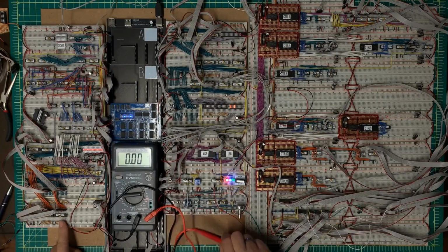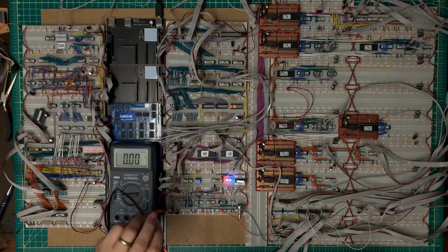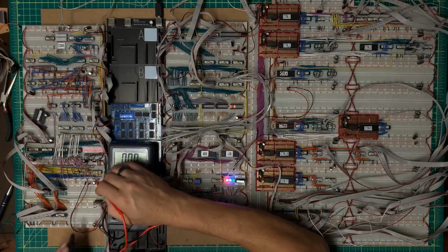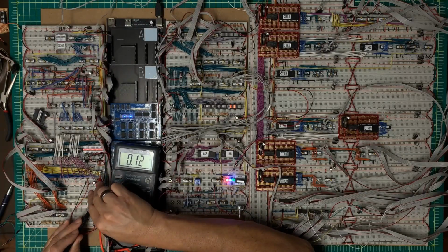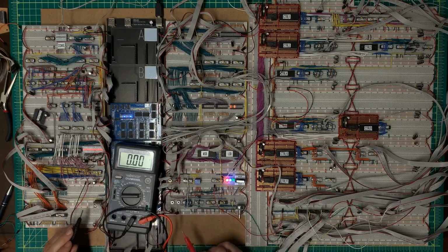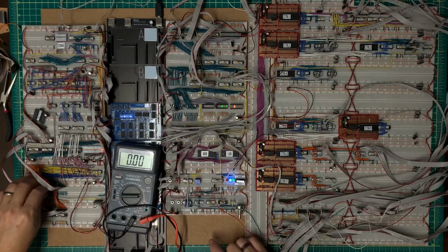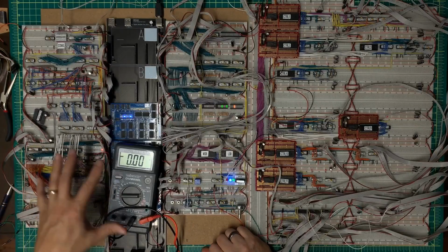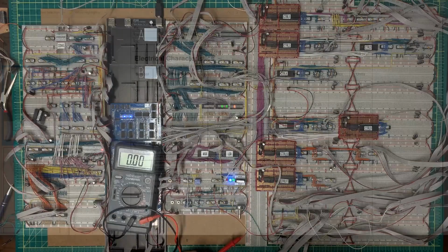Now, to make matters even more interesting, I have LS line drivers here for ALU-B input, and if I check my B input over here, I legitimately have a low input, 0.12 volts. And again, if I disconnect ALU-A from the adder completely, I come out of reset. So there's something going on here with this adder circuit that is really perplexing me.